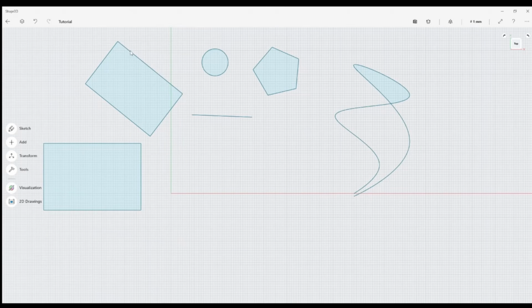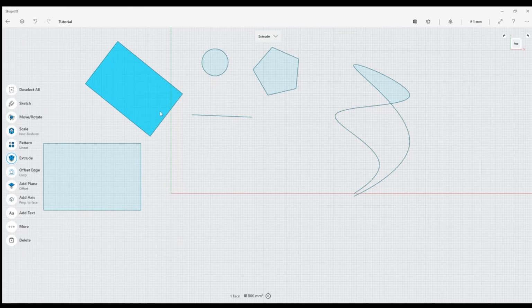Now you notice, and we will be getting into this more in the next tutorial, where we're talking about how we are actually designing things. We'll do our first initial design, but once it's blue, that means that it's completely enclosed and it's a valid shape. As you can see here, these are not closed off, so this area is not blue. I can't do anything with it. This area is, however, because it crosses right here, so I'll be able to extrude that. We'll talk about that more.